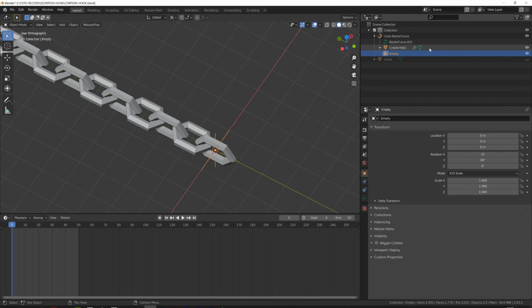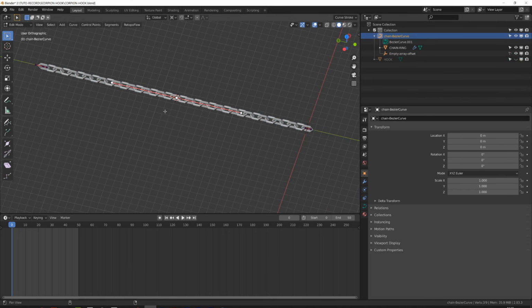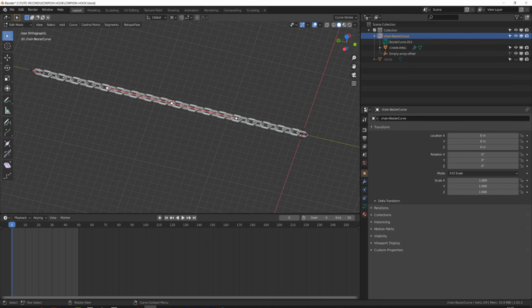They can be any kind of object, and we can bind any controller point of the curve and its tangent to it. So we could do it directly with bones, but for the sake of organization, I will first use empties to do it. In edit mode, on the curve, I will select the last controller point and snap the cursor to it.